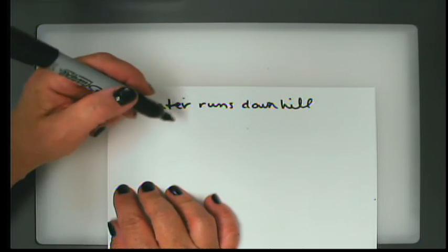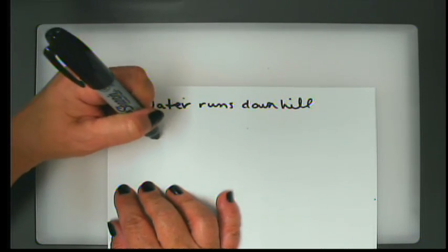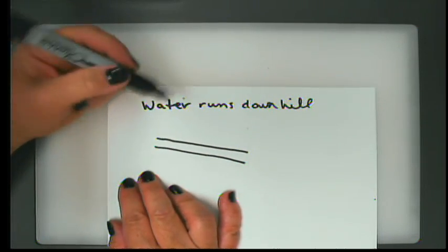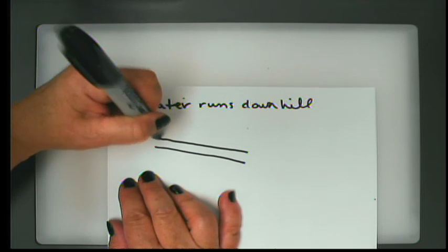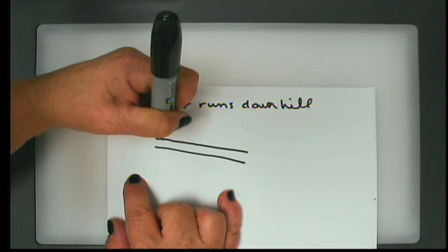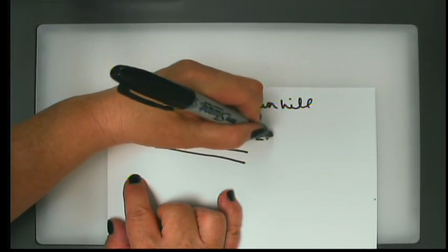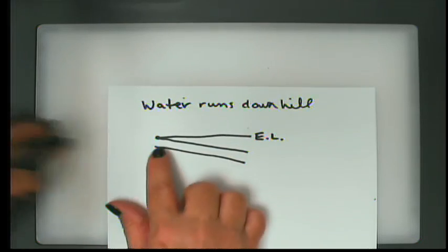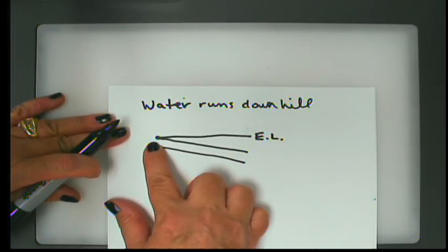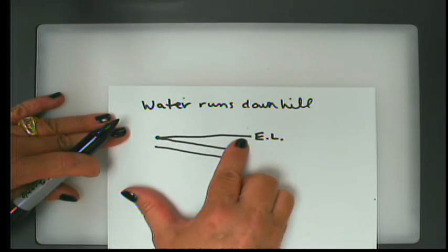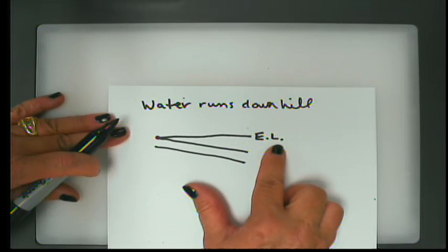But what this really means is, let's say you have a pipe that's running water downhill. If your energy level starts right here and you equate the energy to an elevation, that water will never pick up any energy unless you put a pump or a turbine in it, right? So that elevation is actually the total energy in the line.